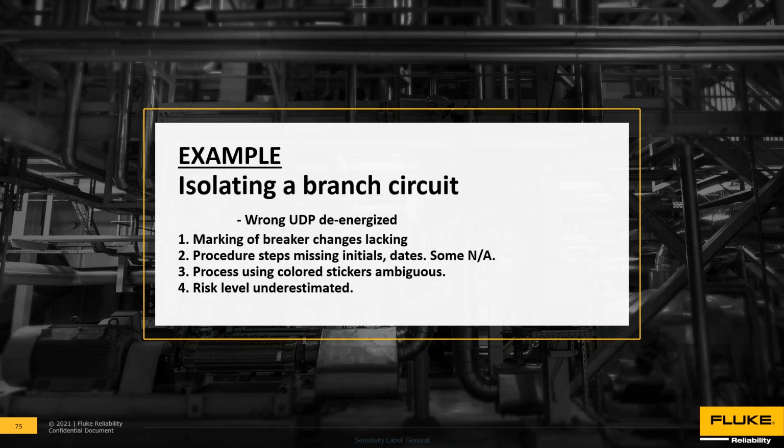Another thing in data centers, we provide electricity to servers, and a big thing is redundancy. So all the servers have at least 2 power feeds. If you're going to do maintenance and you open the breaker, you want to make sure you open the right one. And we did not in this case. As I went through this, there were a lot of different things, like marking the breakers. We had a procedure with a lot of steps. Some steps were marked NA that shouldn't have been. Some of them were sloppy. They didn't have the guy's initials. They didn't put a date in it like they should. There's a column for it.